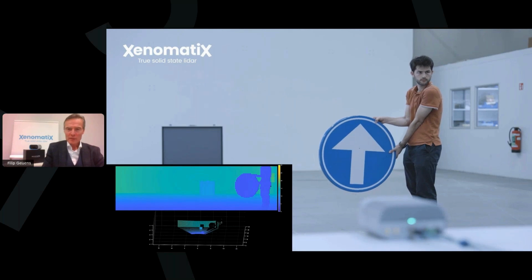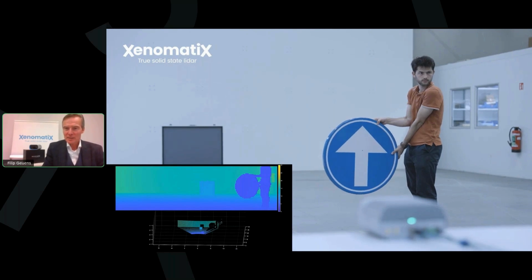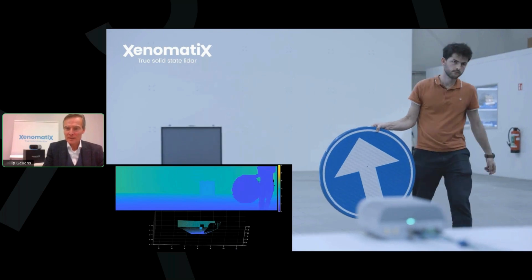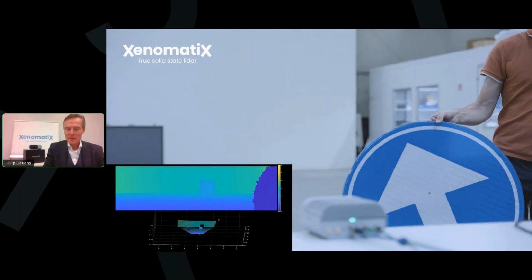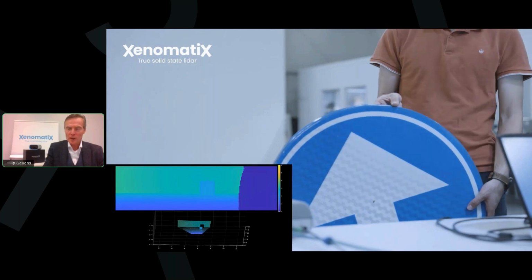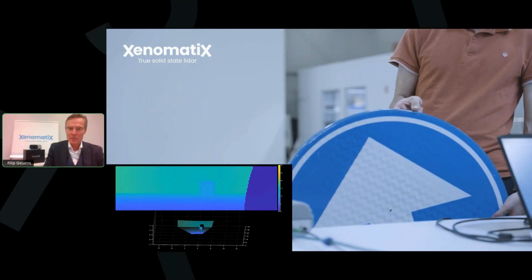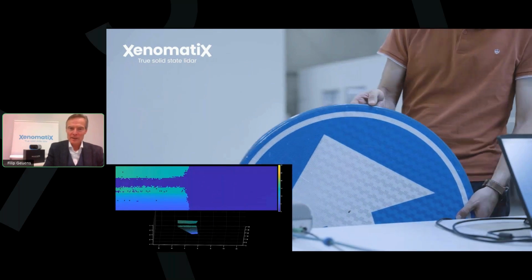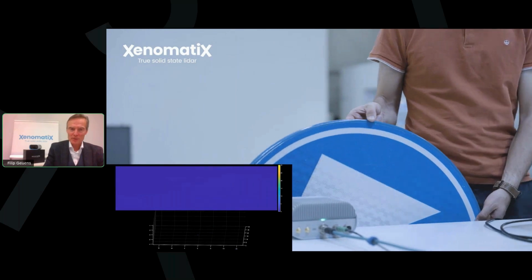And we're going even to go to the next level. Let's bring this reflector at a few centimeters in front of the LiDAR, trying to blind it, but that's not happening. You can see the LiDAR, the traffic sign is partially covering the view, but now traffic sign at a few centimeters and 10% reflective target in the back, both are visible, and the point cloud remains very, very sharp.